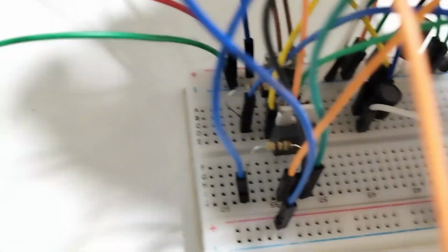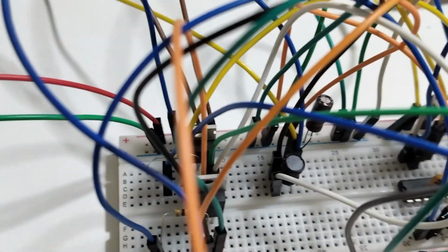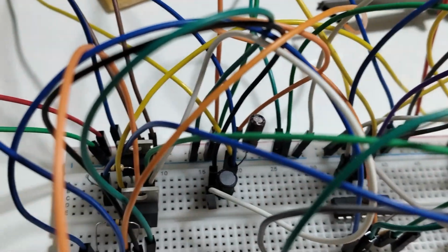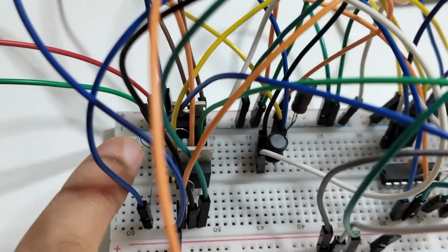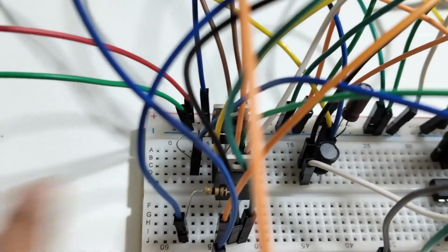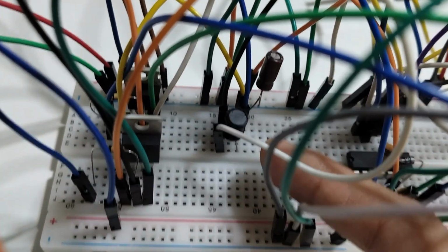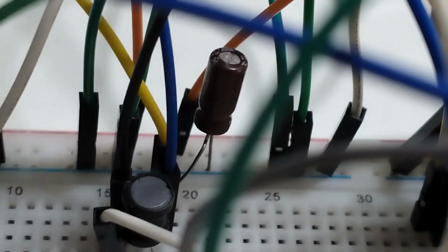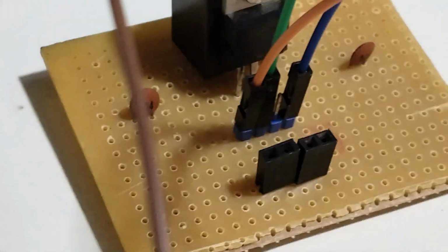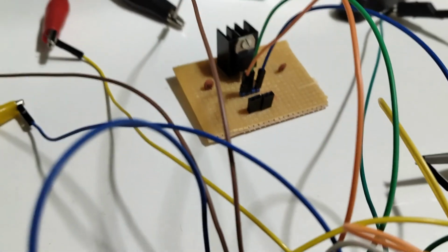The one which you see on top here, that is the high side MOSFET, which is standard. And you can see there's no diode anymore. This is the low side MOSFET, which is going to be replacing our diode. And both of them need the 10 ohm gate resistor. It's a choke type or radial type inductor there. And we have the electrolytic capacitor, 47 microfarad. And as I said, we need 5 volts for the optocoupler. So a 7805, just run on a perf board separately.